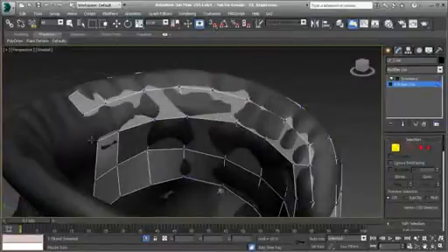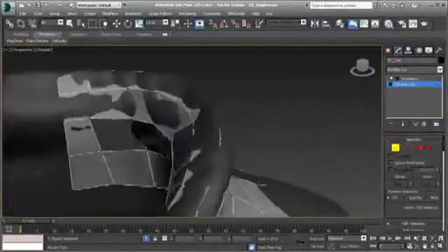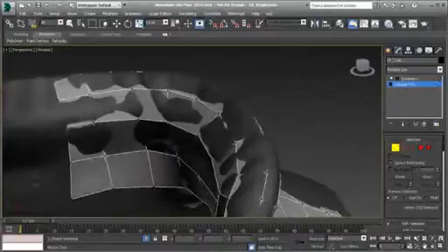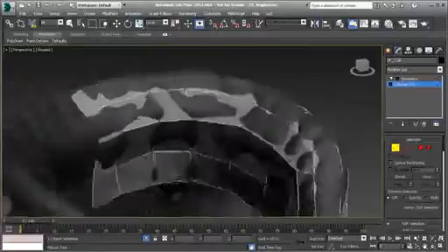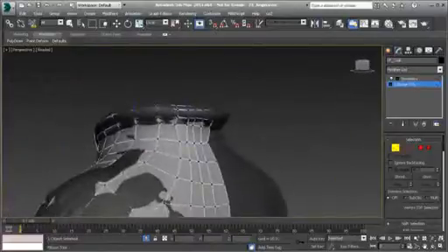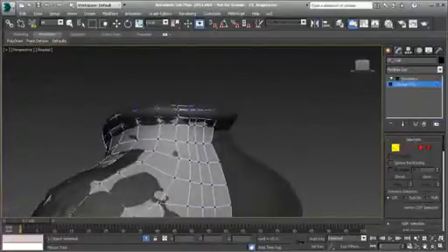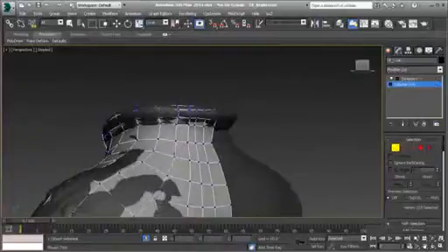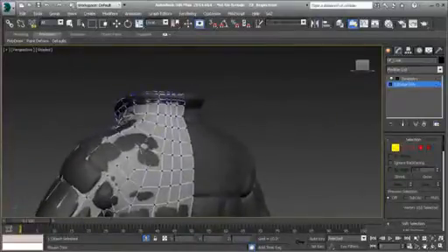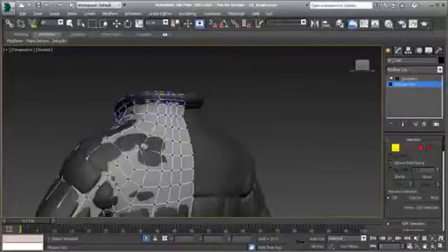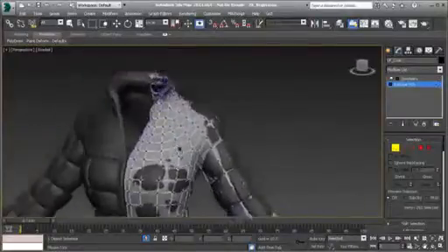And so creating geometry for that, I think, would be okay. So to do this really quickly, let's just simply apply a shell modifier to that. Go ahead and set the inner amount to 0.1 and the outer amount to 0. Your segments should be set to 1. You don't really need any bevel for that. And then all you'll need to do at this point is just simply right-click, and you can collapse all, or you can right-click on the object and say Convert to Editable Poly.